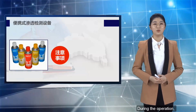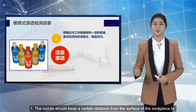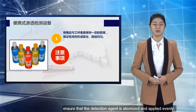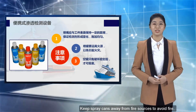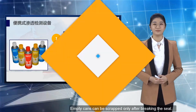During the operation, we must pay attention to: 1. The nozzle should keep a certain distance from the surface of the workpiece to ensure that the detection agent is atomized and applied evenly. 2. Keep spray cans away from fire sources to avoid fire. 3. Empty cans can be scrapped only after breaking the seal.